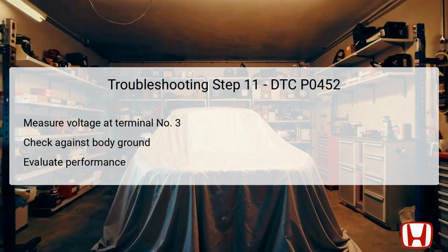This action is vital as the discrepancy in voltage levels may suggest either a fault in the FTP sensor or in its wiring. If the voltage is indeed low, it may indicate that there is a grounding issue or an electrical fault preventing the sensor from operating correctly. Subsequently, this examination will guide further troubleshooting efforts towards either a wiring repair or sensor replacement as deemed necessary.